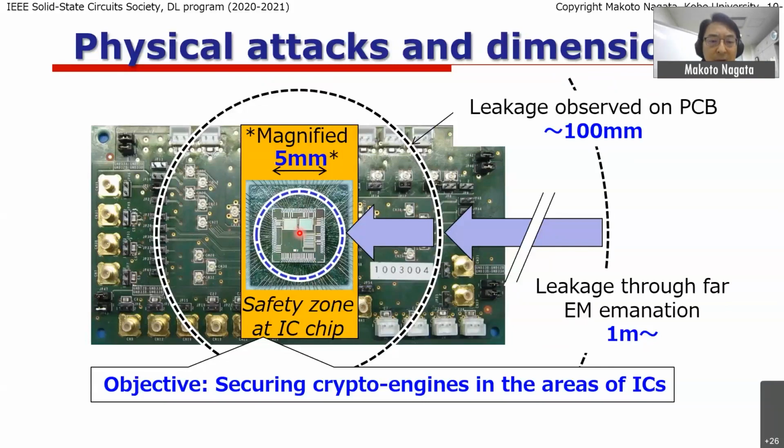And the antenna can come closely to the surface side of the die. But obviously, we have the printed circuit board. In that case, the antenna can scan over the whole board. Or even in a bigger room, you can have a big antenna that can capture the EM noise or EM radiations coming from the operation of the die.